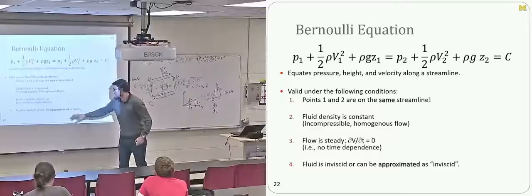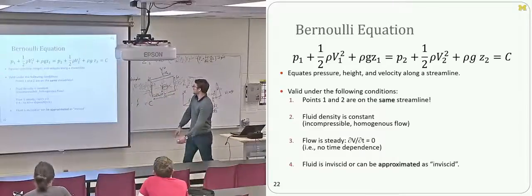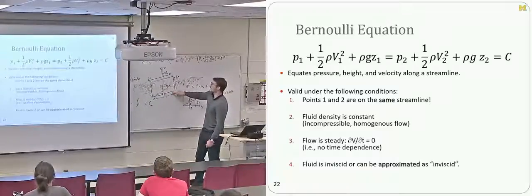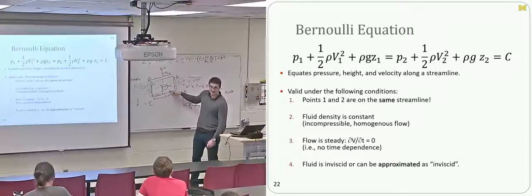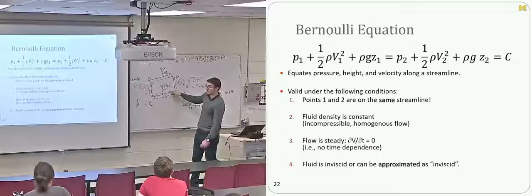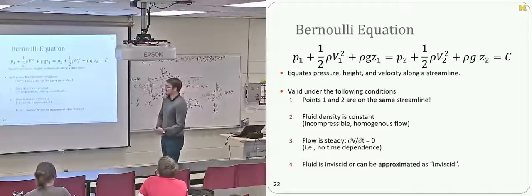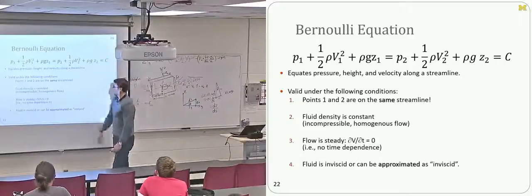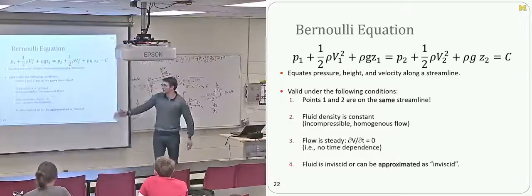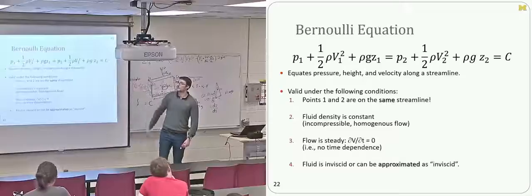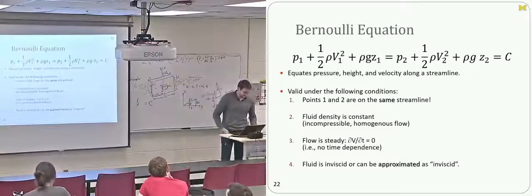And the fluid has to be approximately inviscid, because in this free body diagram, we left out all of the frictional components, which would be acting on these faces, right? Shear stresses were left out entirely. Please, please, please commit these conditions to memory whenever you are using the Bernoulli equation. You're going to be using it a lot.